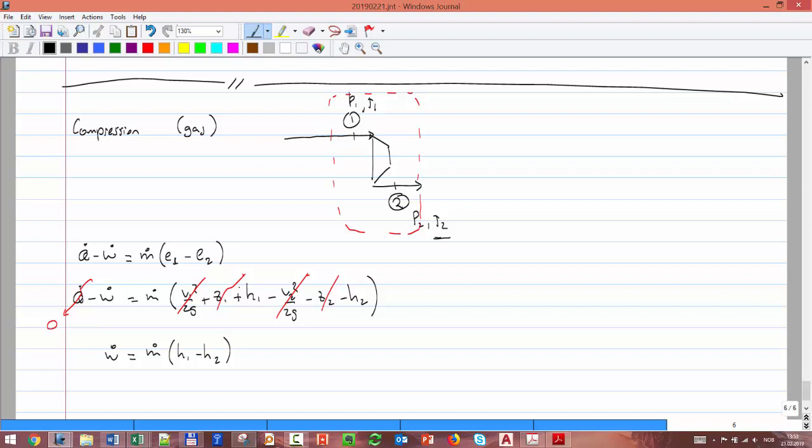Okay, that's okay. So this power is the energy of 2, which is usually bigger than the energy of 1 because I'm adding energy to the stream. Therefore that difference is negative, and that value is negative because I'm introducing work to that volume. So at least it makes sense.